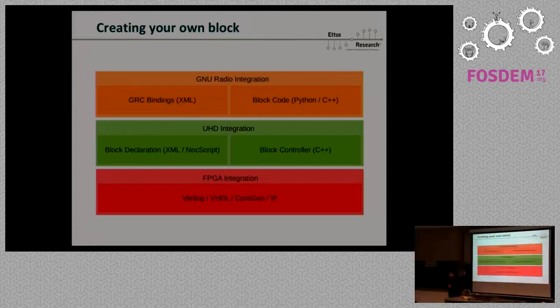Then you have your block controller. If you have more than one input, if you have something going on with the driver, if you're actually going into the connection between the FPGA and the host, you're going to have to write that C++ file. Usually, you don't. Usually, it just works with the descriptor because you have something that is called NoC script. That is a way of instantiating or creating some small functions in your descriptor so that you don't really have to write a block controller, right? And then you want to have GNU Radio like blocks that you can connect and they will look really nice. Then you have to go a step further.